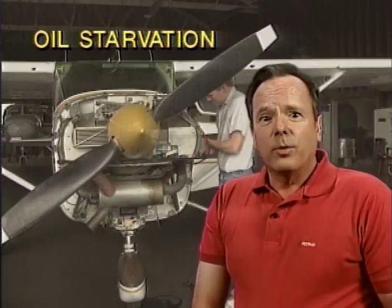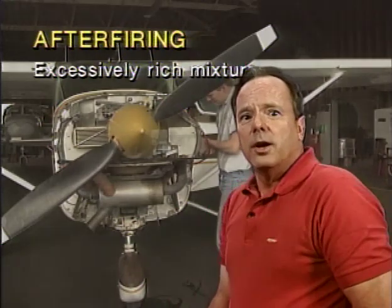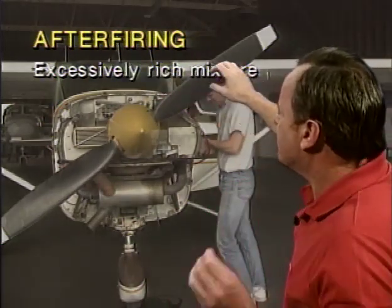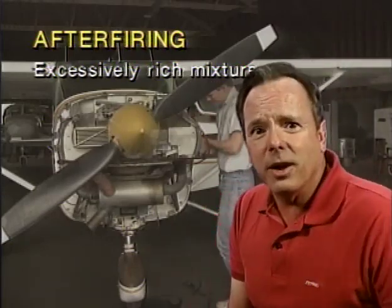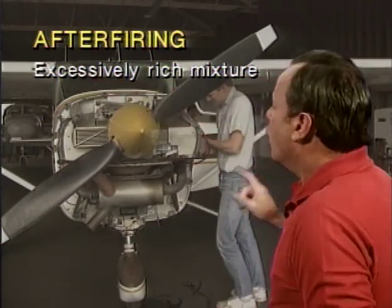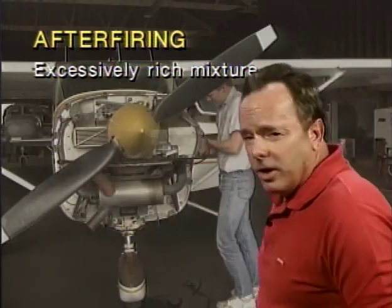Now, another thing they want you to know about is if you have an excessively rich mixture, what's it likely to cause? And the answer is after firing, because you have deposits in there that retain heat and can cause the engine to fire even though you don't have spark on it. So if you have an excessively rich mixture, one of the things it can cause is what is known as after firing of an aircraft engine.